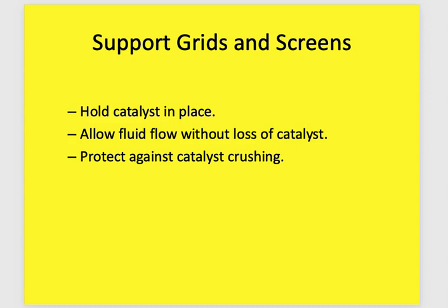Hold the catalyst. You will put the catalyst on this support grid and allow the fluid to flow without loss of the catalyst. Protect against the catalyst crushing also.